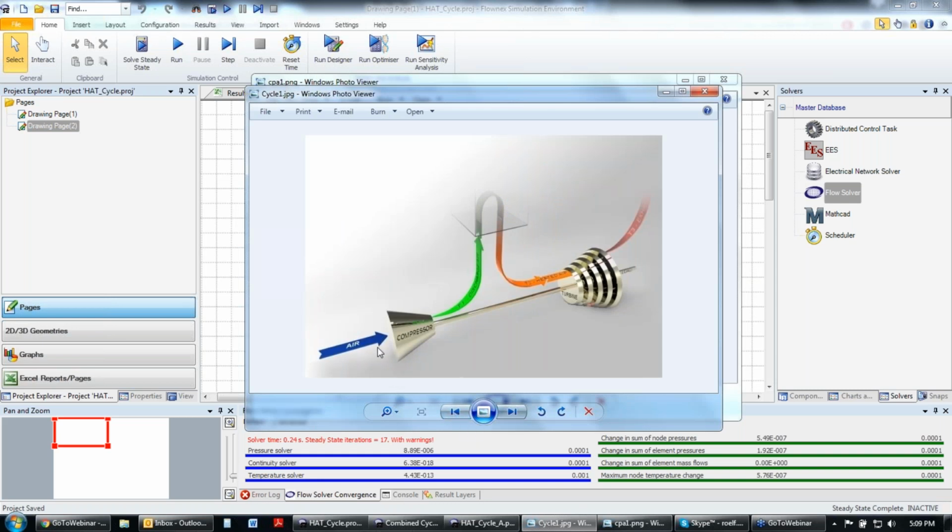Here's another image. You can see the compressor, and as the air goes through the compressor, it will go into some box here, and then out of the box back into the turbine. What happens in this box is there will be some heat exchange, whether through a recuperator or anything, in order to increase the cycle's efficiency. But in our case, we will also have the water coming in here, or the water vapor coming in here. And then also, obviously, we need a line in order to include the fuel.